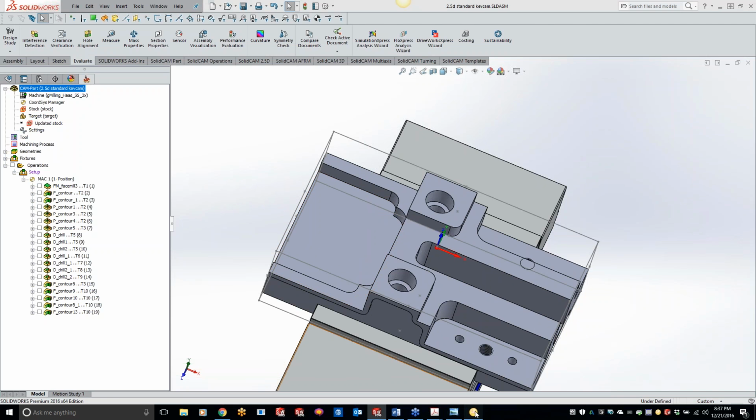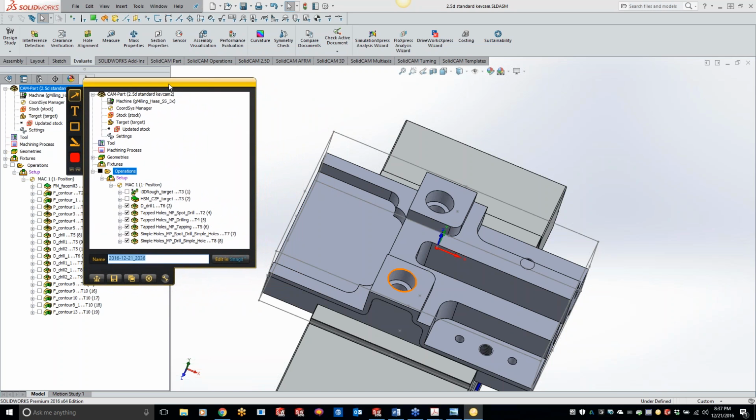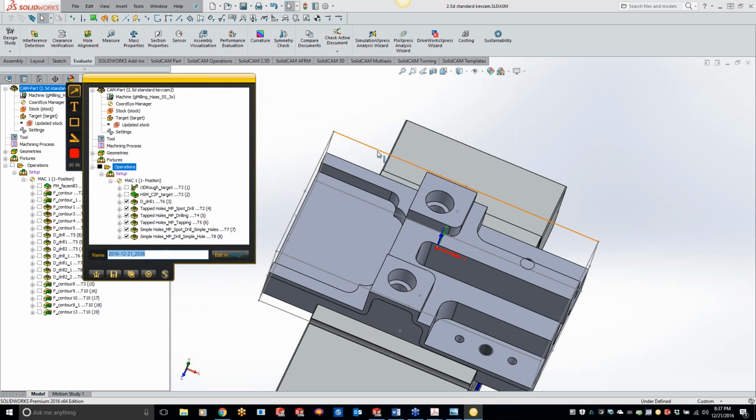Okay, so I'm going to bring up our little screenshot here and match it up right here. We have half the operations and half the cycle time, just by switching from the old 2.5D stuff up to the 3D stuff. So for those of you that already have the 3D iMachining and the HSM, definitely here's where to take advantage on your 2.5D parts.